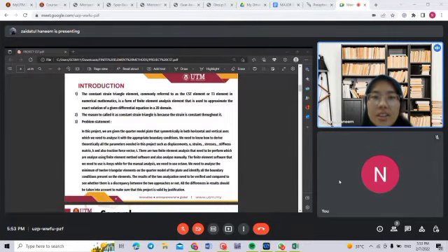The constant strain triangle element, commonly referred to as the CST element or T3 element in numerical mathematics, is a form of finite element analysis element that is used to approximate the exact solution of a given differential equation in a 2D domain. The reason to call it constant strain triangle is because the strain is constant throughout it. For the shape of the constant strain triangle element, it is simple to create a triangular shaped element, which can be used to represent irregular boundaries.